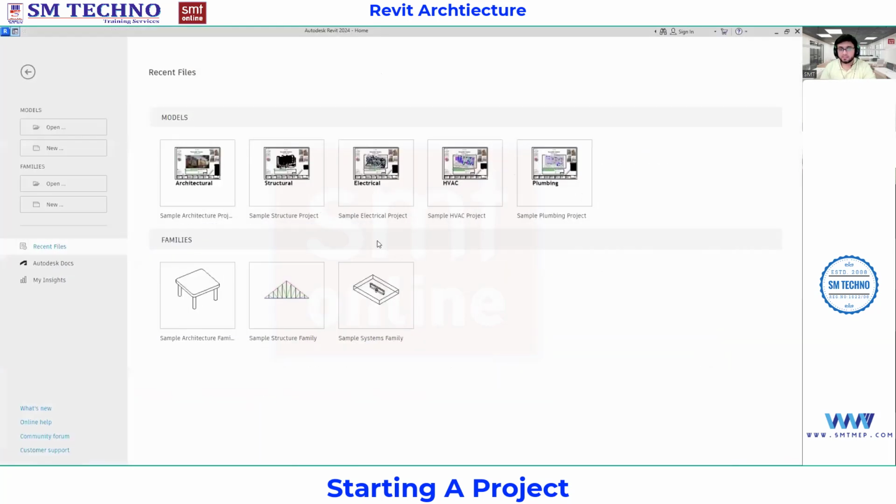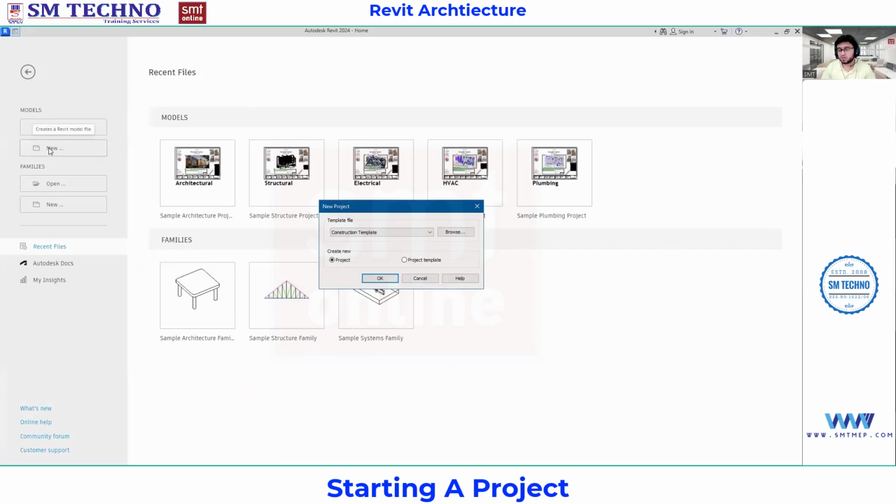Now you can see, by default, when you open the Revit software, you will be getting the welcome screen. In this welcome screen, we have got an option of model. In the previous versions, you'll find the model as a project. So select the option of new from here. In the model, select the option of new. By default, you will be getting some templates. Like, which domain are we working with? We are working with the architectural domain.